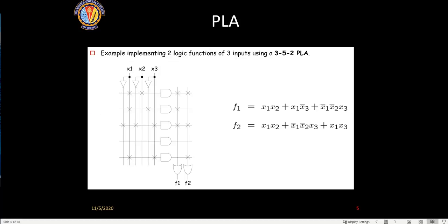Just to clarify, the horizontal lines on the left side, they are connected to voltage sources, right? Yeah. Are all of those 5 volt? No, that depends on the family. The CMOS family can have other voltages, while the TTL family will definitely have 5 volt. So it depends on the family, logic 1, logic 0.